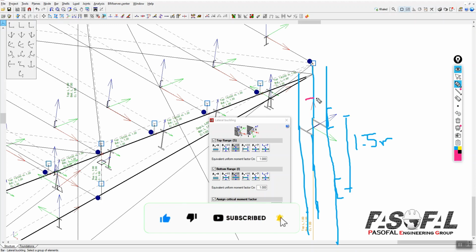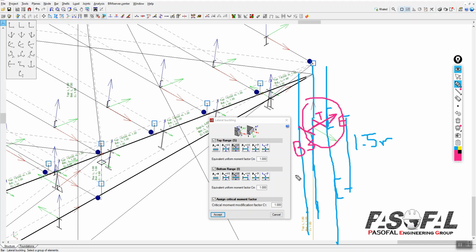If you look at the local coordinate system that you have here, this axis is exactly parallel to the height of the column or section. So that's why here you can say that it is the start point of the axis, and here it is the end point of the axis. So we can say that this one is the bottom plate, or bottom flange, and here this is the top flange. Okay, so again, it's very easy to understand, not only for the beams, also for the columns. Simply you can understand which one is the bottom flange and which one is the top flange.